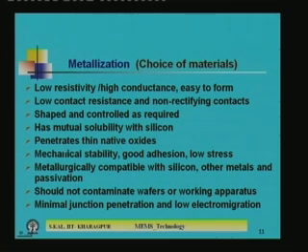Okay. Next is penetrates thin native oxide. When you deposit metal film on silicon, you will not always get bare silicon, and a native oxide will be there, even if you clean the wafer and then go for a buffer hydrofluoric acid dip. When you are transferring the wafer into a vacuum chamber for deposition of metal film, during that period a thin layer of native oxide, maybe in the range of 2 to 3 angstrom, will be formed, and that native oxide is very difficult to remove from the silicon.